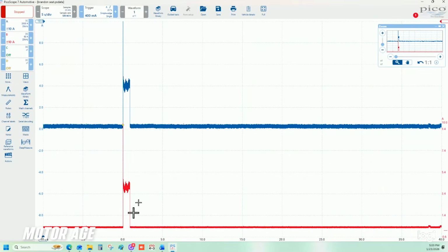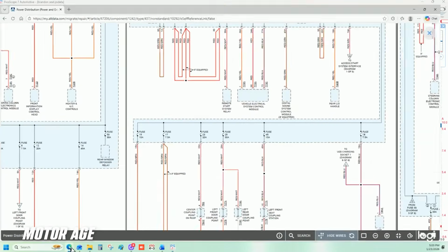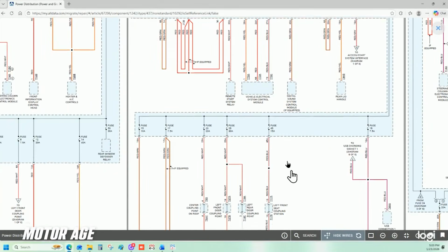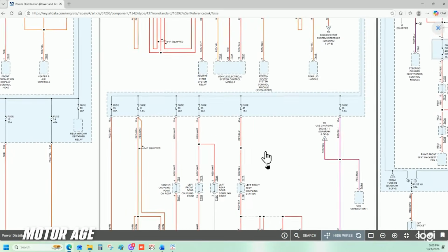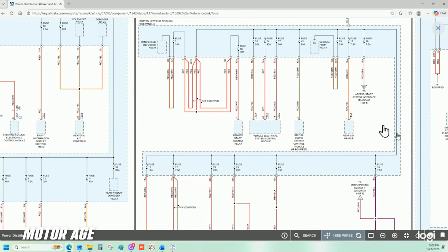So there really is only 2 or 3 circuits supporting what we see here as far as the operation of a DC motor, meaning we don't have to check all 15 or 20 of these, only the 3 that would produce a DC motor output. So that approach is a real time saver if you take the time to understand what the tools do and how to leverage them to your advantage.